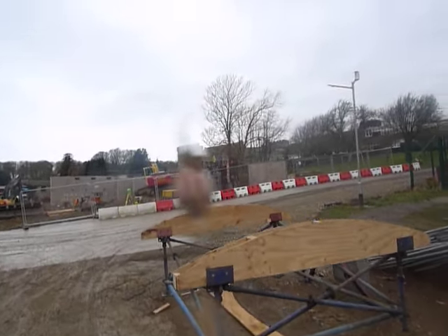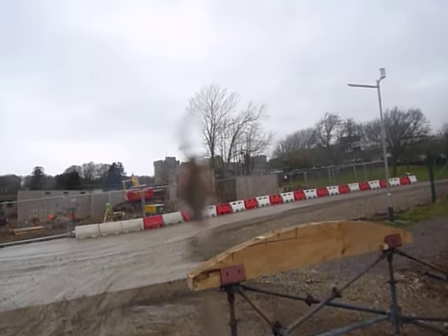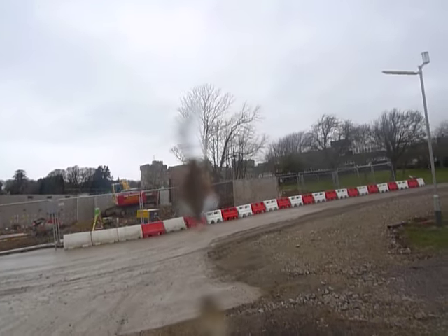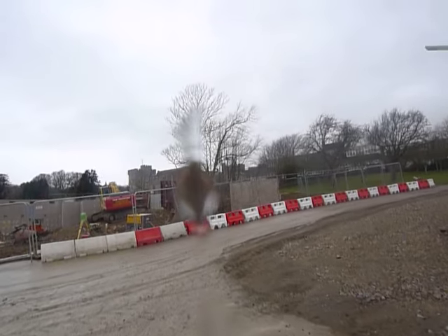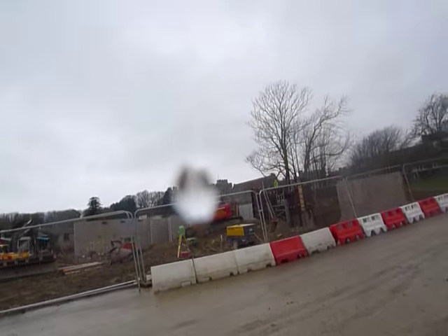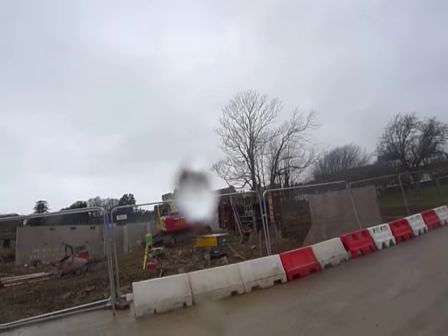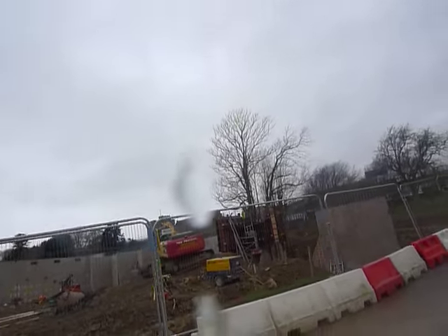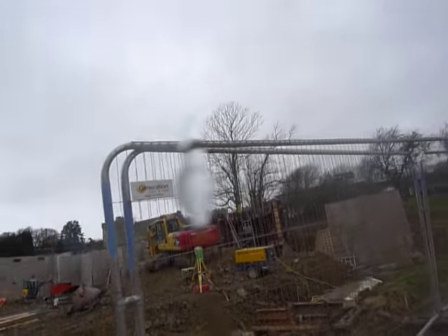So the speed of the concrete pour is very important when you're doing this shuttering system, because it's a 3-meter high wall, and if we're trying to discharge, it actually takes about 8 meters of concrete, okay? So we can get an 8-meter concrete wagon in and complete it in one go, really.